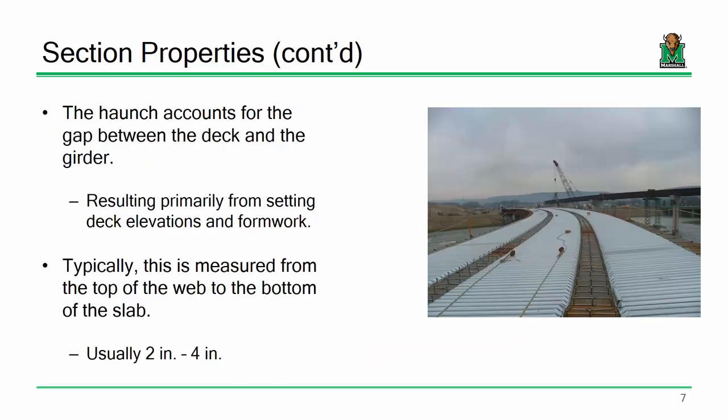Okay? Now, does everybody understand what's going on with the forms and why it tends to be raised up a little bit? Okay. One thing to keep in mind is something I've been pretty fast and loose on. We will actually spend a fair amount of time this semester looking at just the studs themselves and actually figuring out how many studs need to go on the beams and in what spacing. The only point I'll make is if you look at a steel beam in a building as opposed to a steel beam in a bridge, there is an ocean of studs on bridge beams, okay?